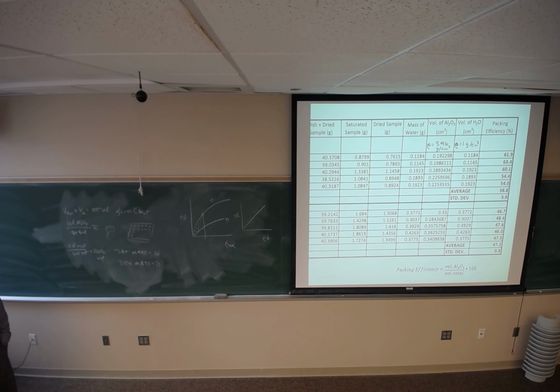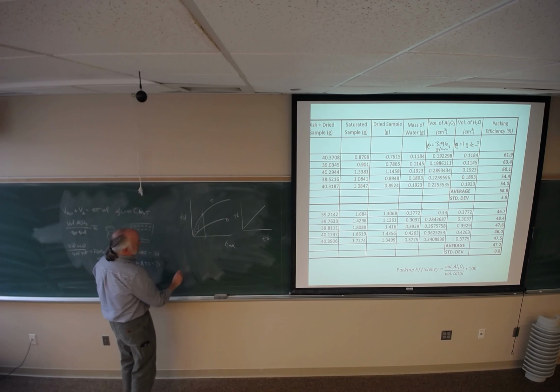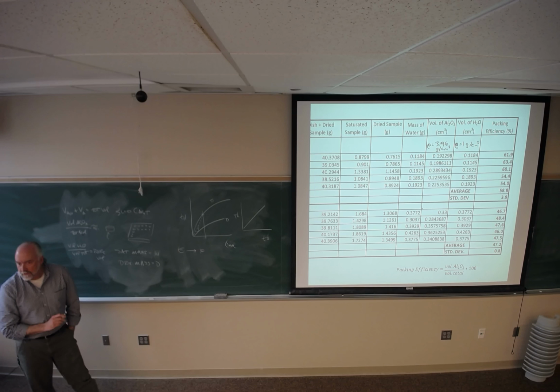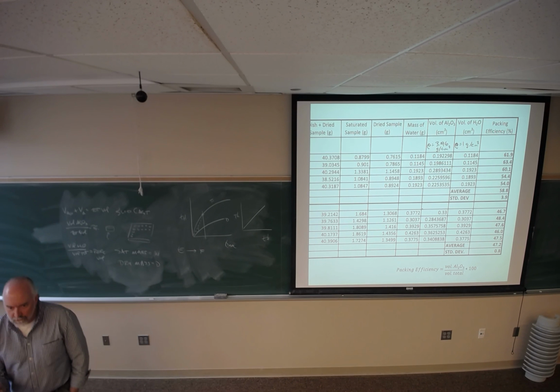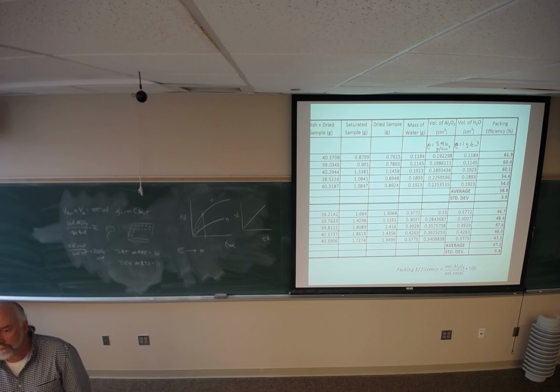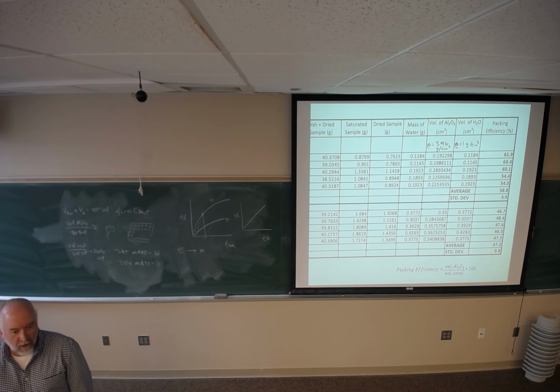There's one other thing. For extrusion systems, you work with a flocculated suspension. You are welcome to try a dispersed suspension. Okay, it typically doesn't work well. And the reason is that flocculated mass is a compressible system. Dispersed mass, because particles pack so highly, there's no compressibility. Okay, so it doesn't work well.